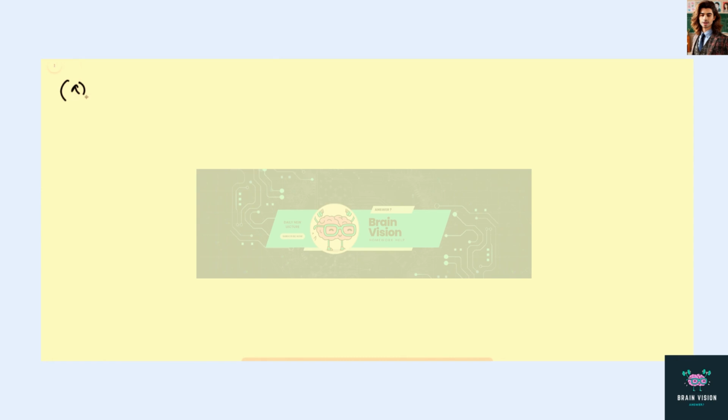If the terminal voltage is to be 3 volts, then the voltage across R1 will be 9 volts. So V1 will be 9 volts. Now this can be used to find the current, which will then be used to find the value of R. So let me just write the equation so it will be clear what I mean.